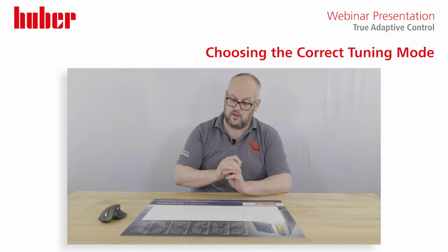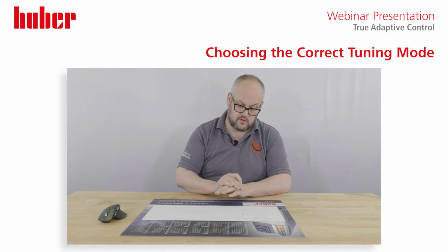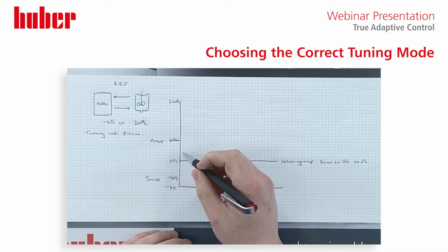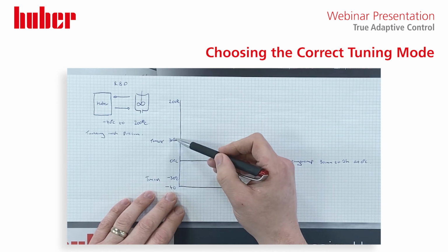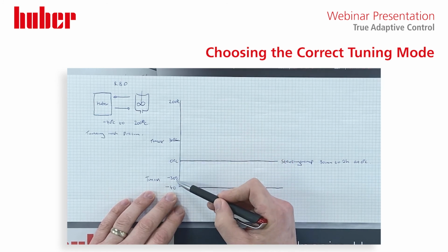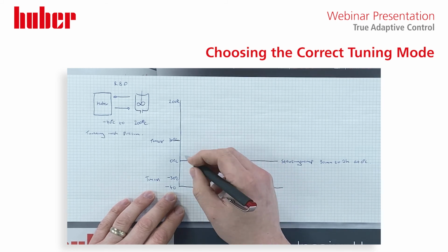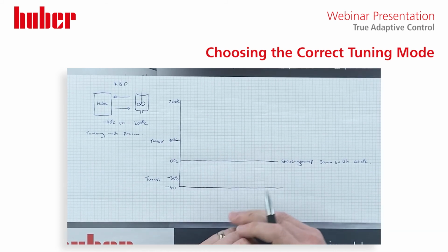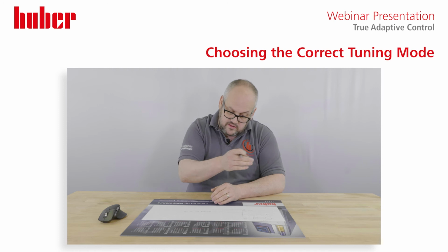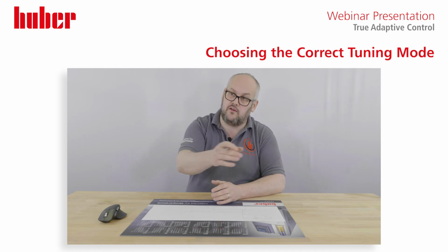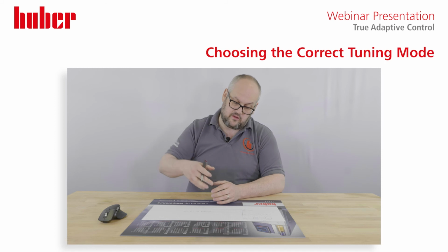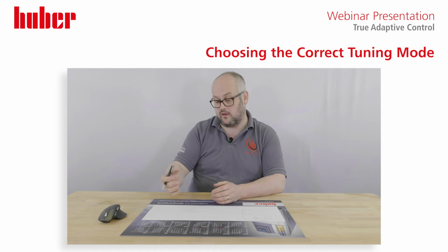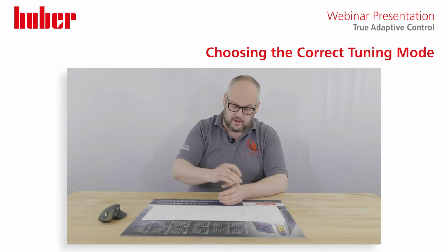We know our external PT100 probe is stable, the agitation is stable, we're not generating heat from the system. And what you'll find is, because we've now curtailed a T-max of plus 30, a T-min of minus 30 in our system settings, the unit will do its initial dead zone finding. So like in the fast tuning, it will send little packets of thermal information and try to ping the different sensors. It then calculates using the heat capacity of the thermal fluid and also the volume, a kind of a response time to get feedback.